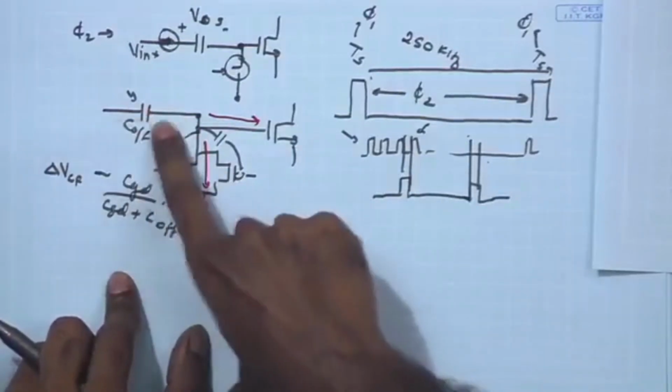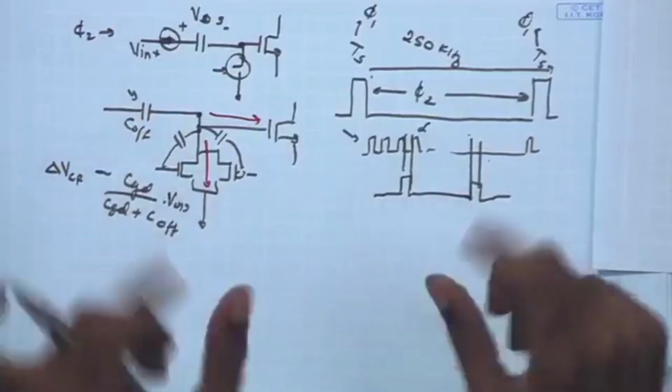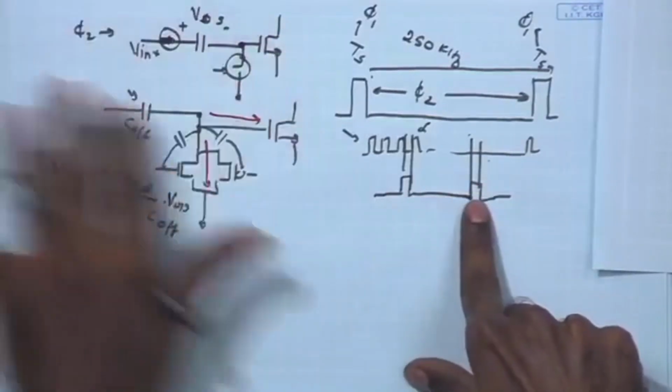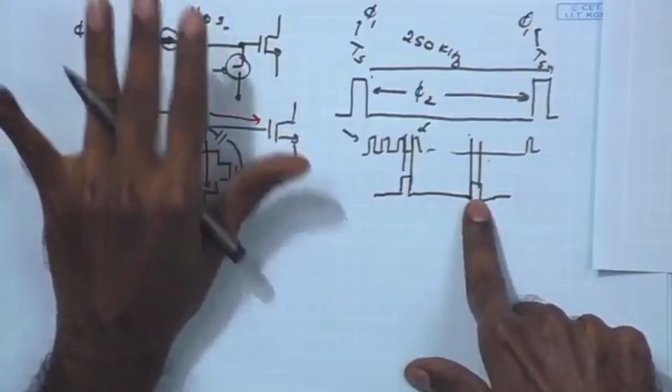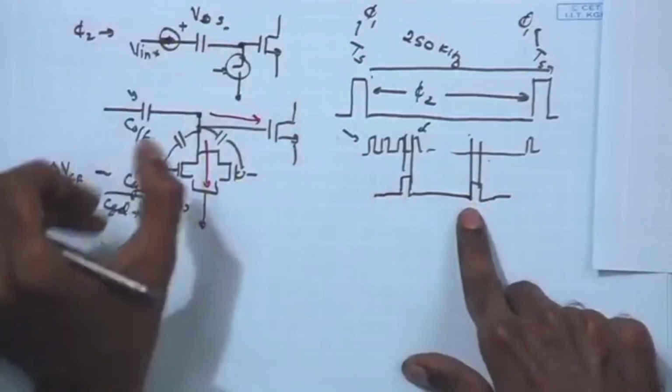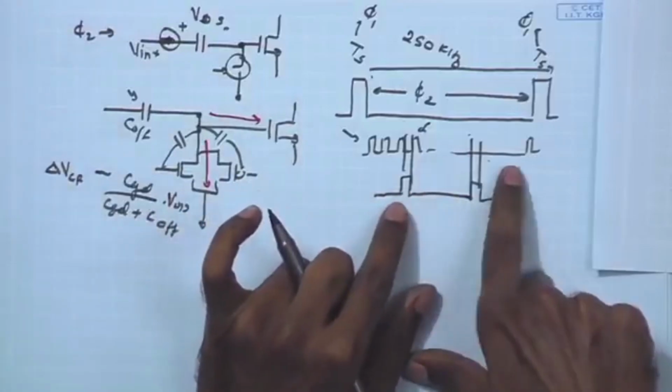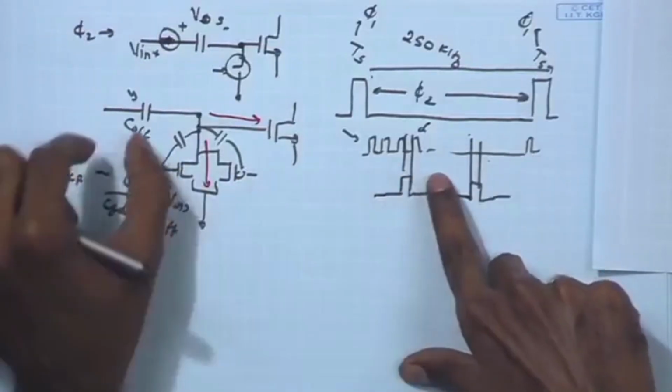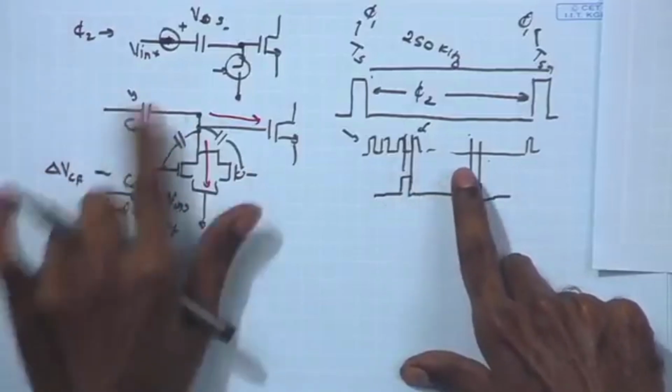So, the timing control becomes more complicated if we are going for intermediate refreshing of the offset voltage across the C offset. We have to make sure that in between we break the normal comparison operation and resort to offset sampling, and immediately after that, once the offset voltage has been sampled again, reconnect the input to the 2 points.